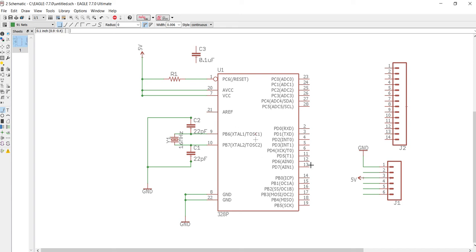So running some of these wires, we would have to run these a long ways. So let's take an example here. For example, this one's RTS. We want to use RTS, and I just click, I'll turn, and then I can terminate it there, and so this line is actually what's used to reset the chip every time you're loading new firmware. But that's a really long route, and we might have a bunch of wires going all different ways, especially as we get into this 14-pin block here, and that can turn into a big jumbled mess.